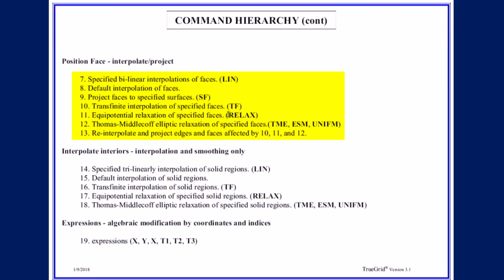So it's back and forth between smoothing and projecting. If you do 300 iterations, 300 times each node is smoothed a little bit and reprojected. Still basically the same idea. It first interpolates and then it projects.